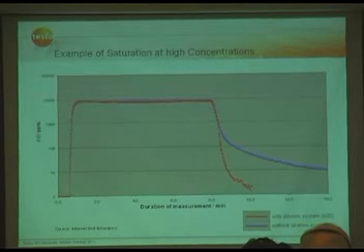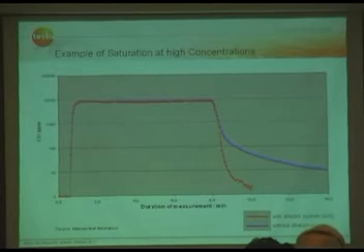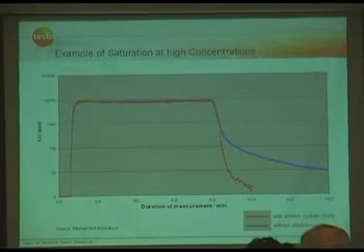That means if you don't make sure the sensor gets to its limits, then you can have a wrong reading after a while. And mostly you recognize this when the measurement is done, and you look at the numbers or the measurement data, and you figure out, okay, the CO reading is wrong because I had a peak of 10 minutes with high concentrations, and then the whole reading is gone and you have to repeat the measurement.